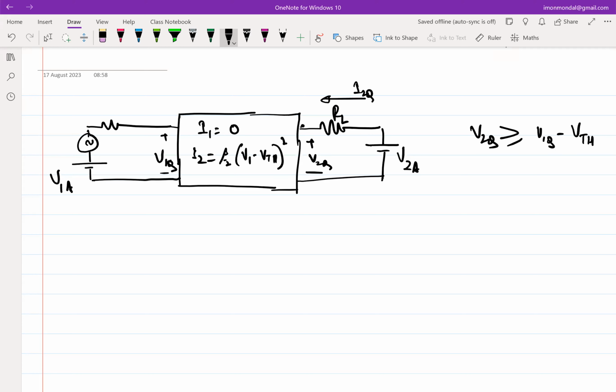So the reason I didn't till now replace the box with a MOSFET was to impress upon you that if I give you a device which does not obey this square law model, but obeys some other model, you should be able to generate the biasing network, apply the input and take the output appropriately, while respecting the requirements of the box. The concept behind this is quite generic, but how you need to bias will depend on the particular properties of the nonlinearity inside the box.